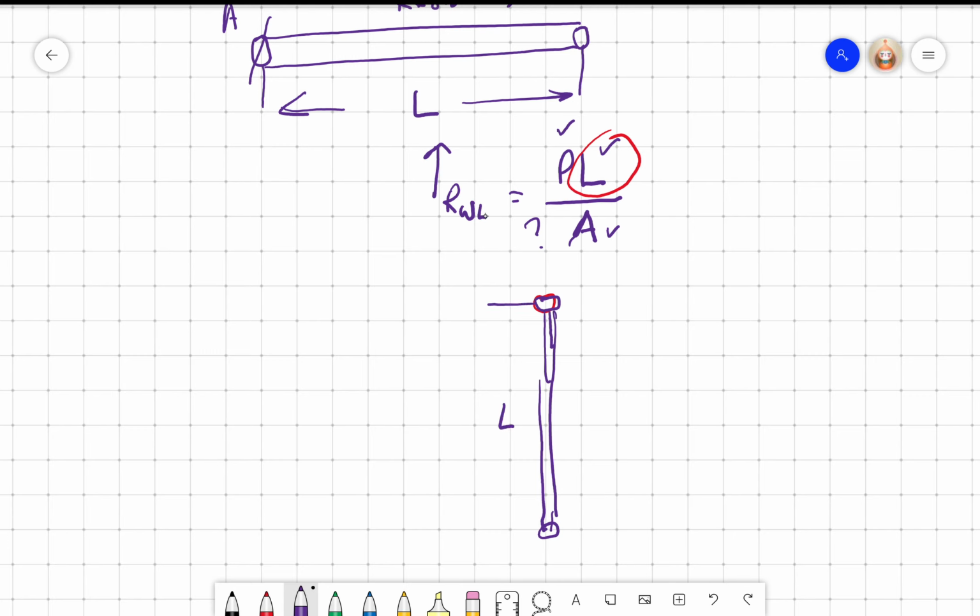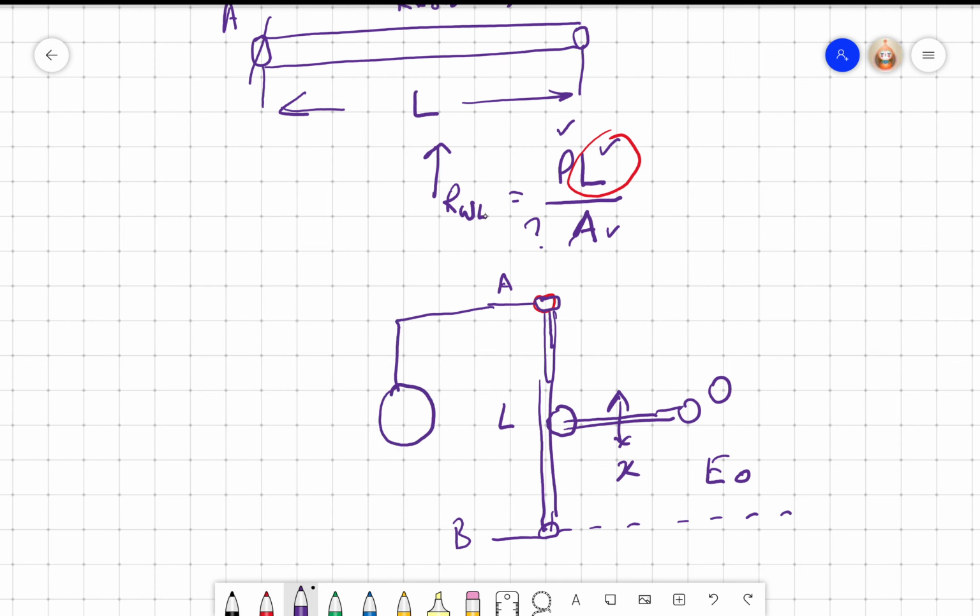I have terminal A, terminal B, and I put a wiper, right, and I move this by displacement x, and this is terminal O. With respect to O, I call this E0, the output. I connect a simple battery across terminals A and B. I have EB,